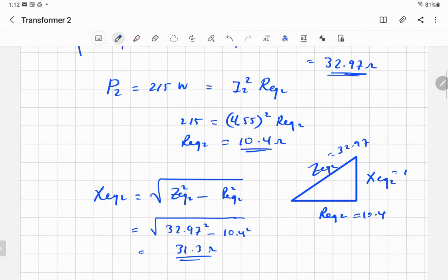You got the X equivalent and R equivalent of the transformer, the total. What's left is nothing, because I have the equivalent circuit of the no load on the primary. Well, take the Z equivalent 2 and transfer it by multiplying by N1 over N2 square, to reflect the impedance. Then you have the whole model of the transformer, the practical model, using the no load test and short circuit test, getting all the parameters without counting the turns, without measuring the wire, just by using measurement instruments.